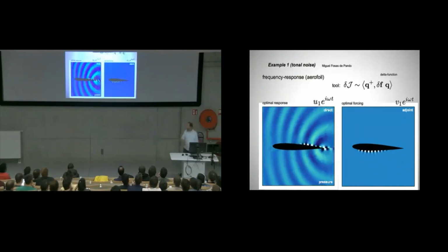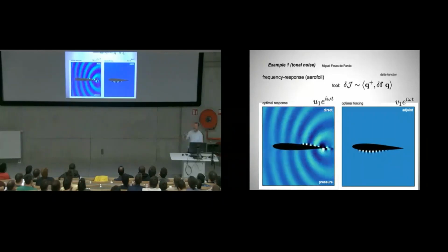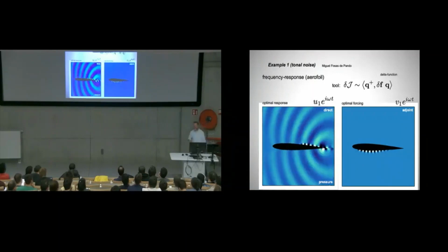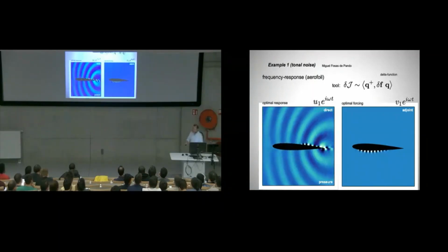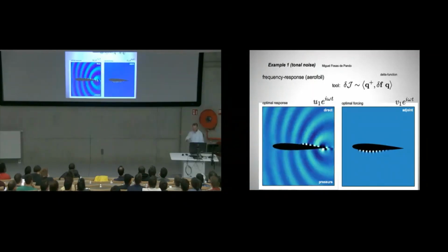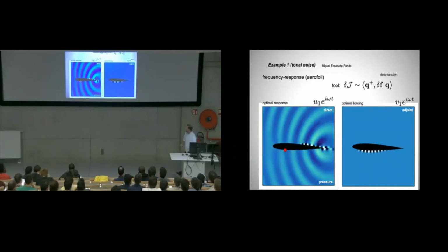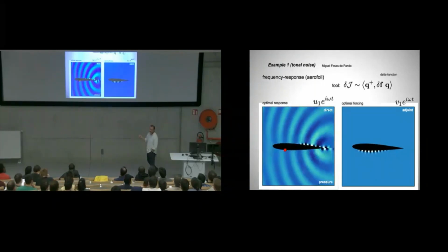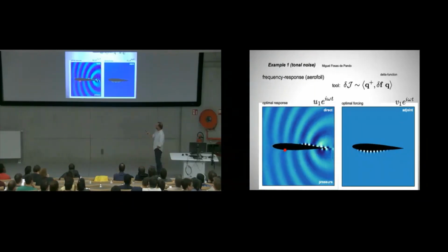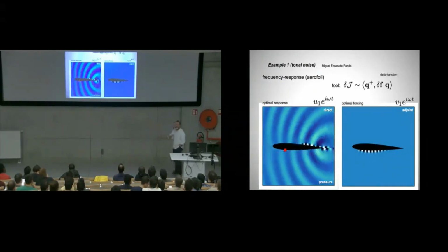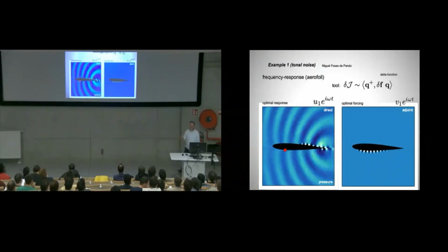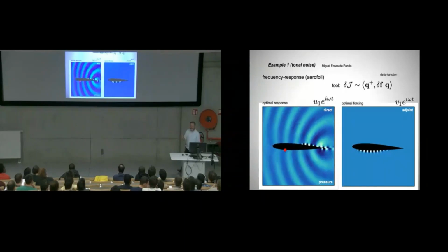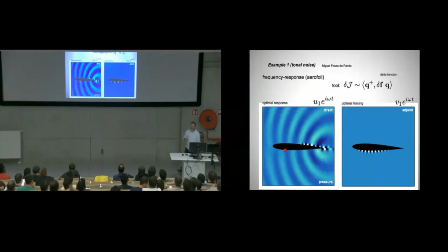Okay? So if you want to kill this one, this is the question for the origin of an instability or the weakest link in the feedback loop. The adjoint and the sensitivity information actually gives you that information. This is the place where you put the wire or a bump or something or an actuator to kill this one. And this is the weakest link of that feedback loop. And it's not on top. It looks like something is happening on the top. That's just the sideshow. Okay? The real sensitivity is in the bottom.